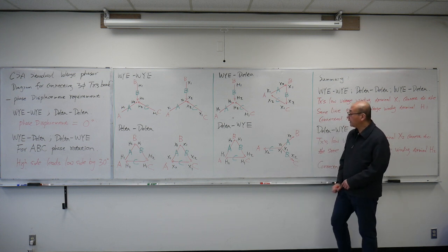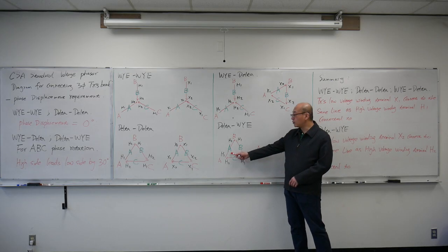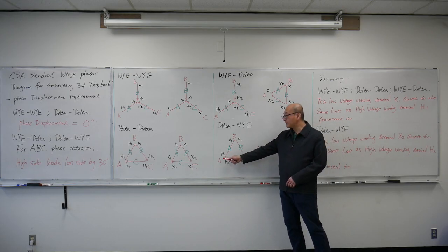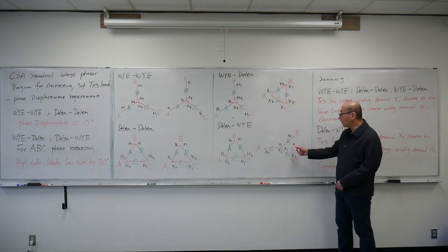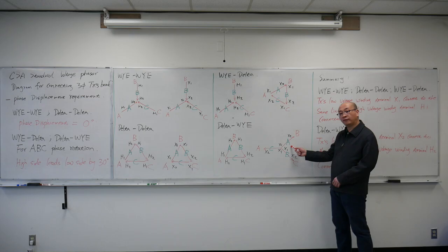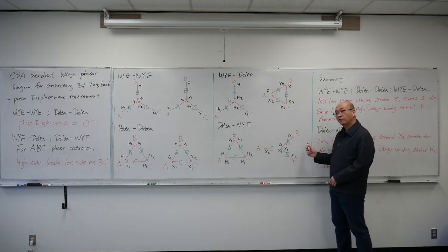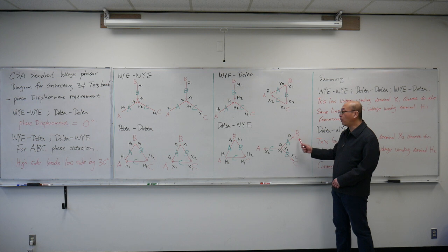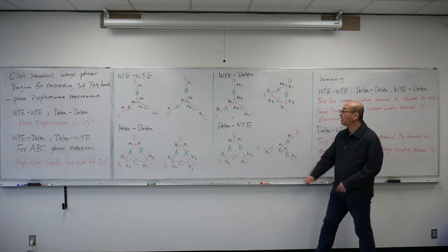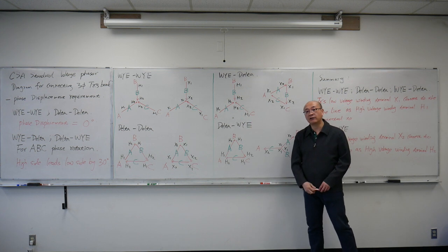The special thing here is that for the phase A transformer, my H1 is connected to A and H2 is connected to B. On the low voltage side, for the phase A transformer, X1 is at the center neutral point and X2 is connected to line B. So delta to Y is something special. You can see the arrow for this Y is pointing out, whereas in all the other Y connections, the arrow is pointing in.